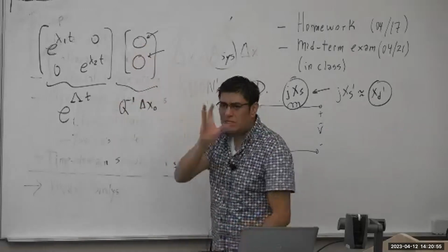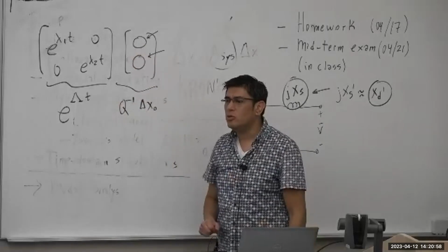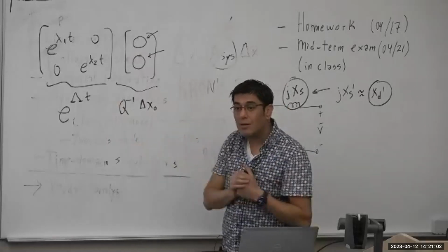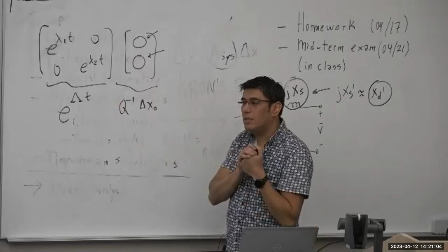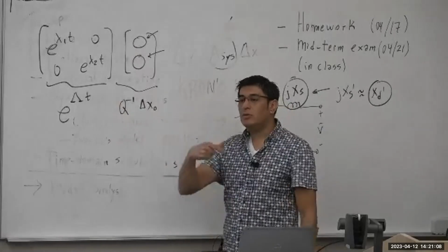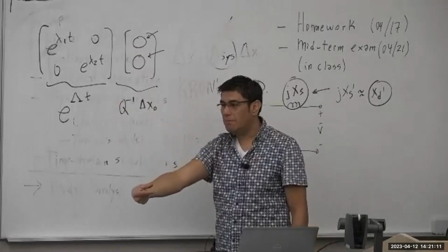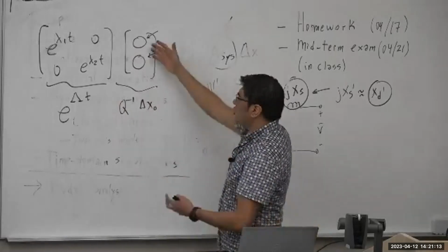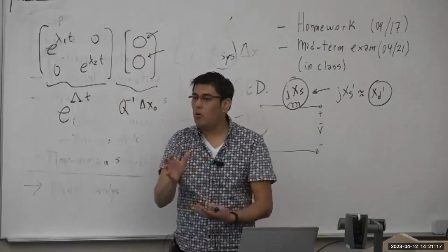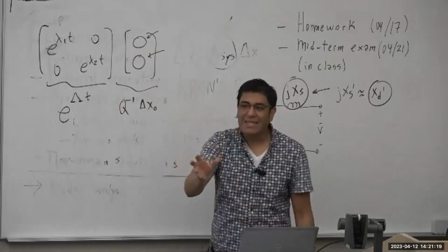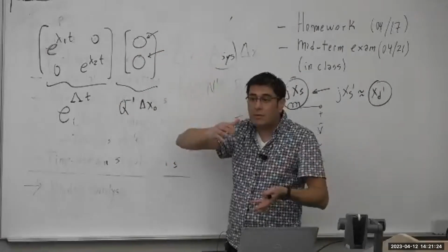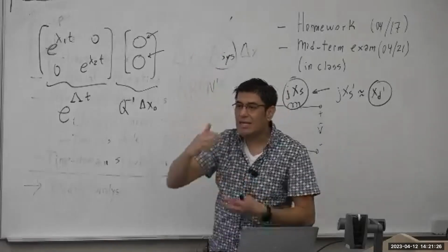What if one of these terms is 0? What will happen in your solution? That mode will not appear, right? Are you following me? So this part is related to the excitation of the mode. This term can be large, can be small. If they are small, that mode has not been highly excited. If that component is large in magnitude, that mode has been highly excited.